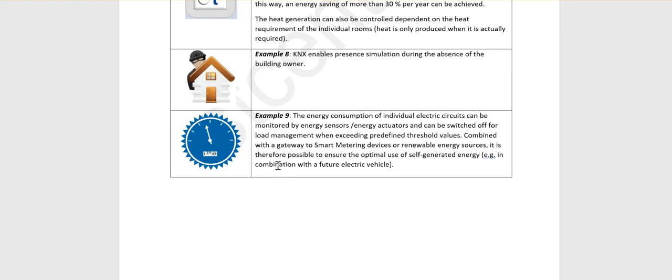And then energy consumption reduction scenarios, you can implement them with KNX devices. For example, you have a dormitory, and you set each room to 21 degrees Celsius in winter. But if somebody comes to the room, uses an electrical heater and increases the temperature of the room to 27, you as an admin cannot save the energy. You lose electrical energy.